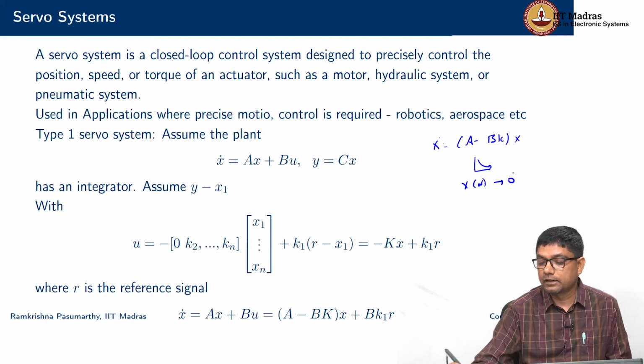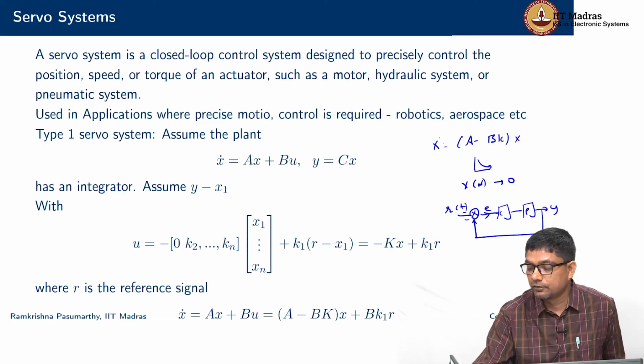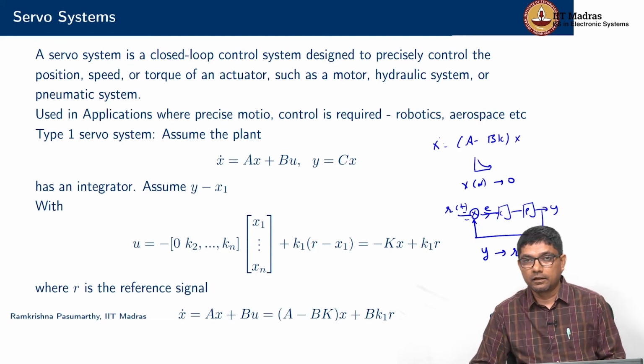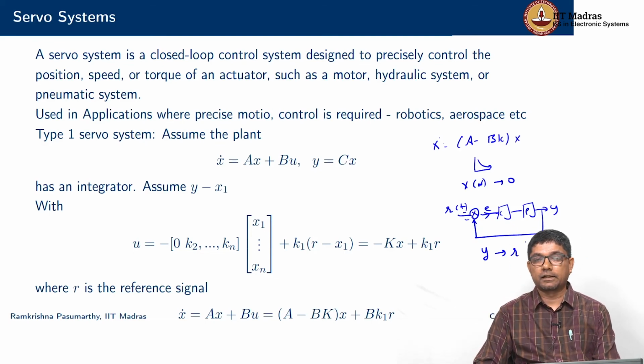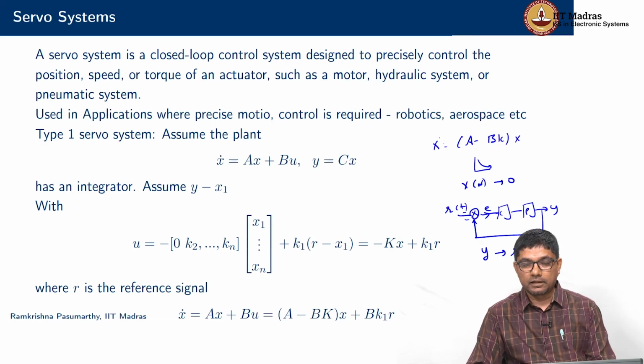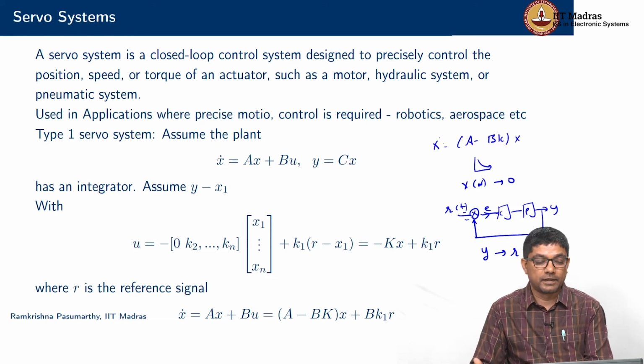Okay, that may not be all the time of interest, because our control architecture had a reference signal, a controller, a plant, output which was compared with the reference, resulting in an error, and such that the y had to track r asymptotically. Those were the standard tracking problems. I want to track a step, track a ramp, or track 10 units of a step, and so on. How do we translate that into problems of pole placement?